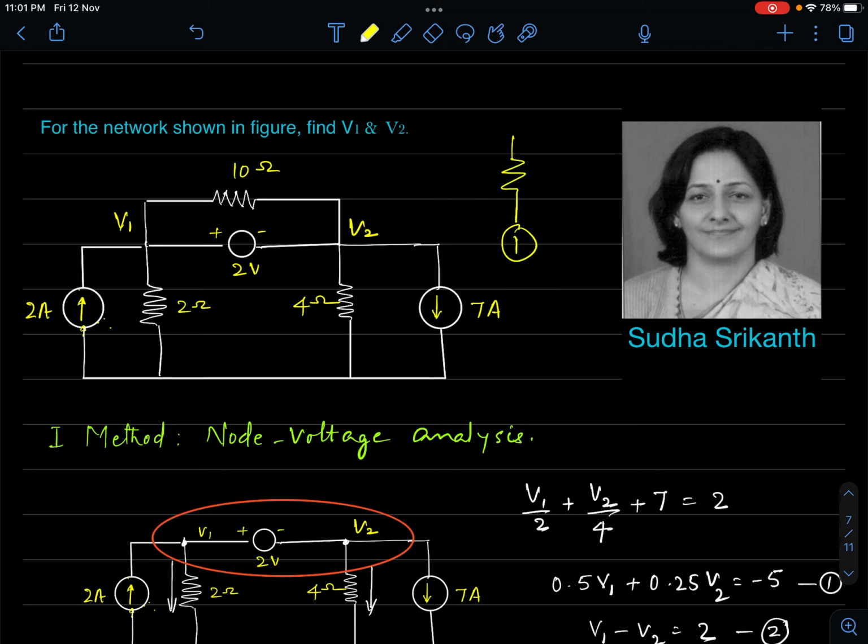Similarly, a point worth noting is if you have a resistance in series with a current source. You have a current source, let us say there is a resistance. What has this resistance got to do as far as this current is concerned? It doesn't have any role to play. This current will pump in I amperes of current irrespective of the magnitude of resistance. So all you can do here, in order to give a path for the current to flow, is replace it by a short circuit. So you can remove the R, but then you have to replace it by a short.